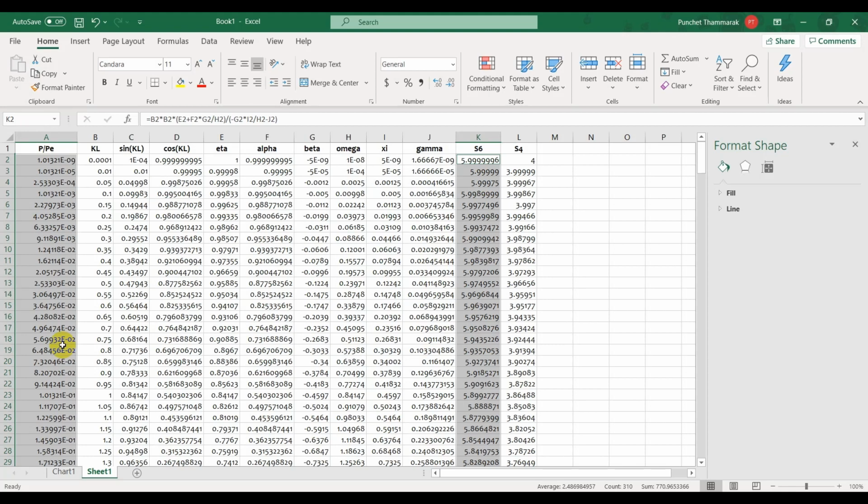So you assume the axial force P first, and then you come up with the PO/PE ratio. You get this PO/PE ratio, you find the S4, S6, S12, S2, right? Plug it into your stiffness matrix and then conduct the structural analysis. Once you finish the analysis, you'll be able to find all reactions and internal forces.